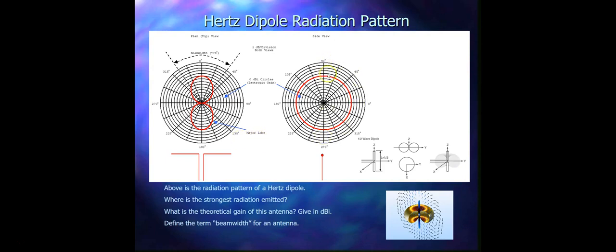And here you see the side view, and it shows the dipole radiation going equally in all directions. On the right-hand side you see another representation of this radiation. This is the dipole antenna represented in the XYZ axes, with a total length of λ/2, and the radiation pattern is represented in the z-axis and y-axis. With respect to this, you can see how it will look for the top view, and for the side view this will be the look.